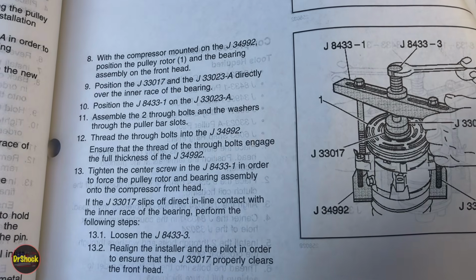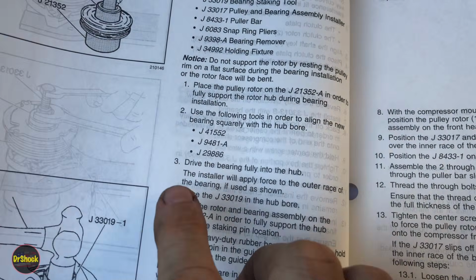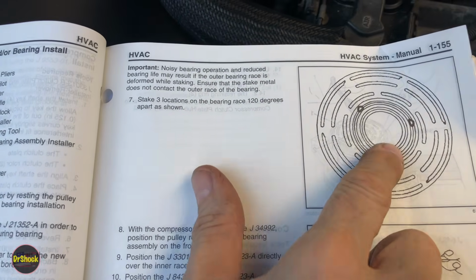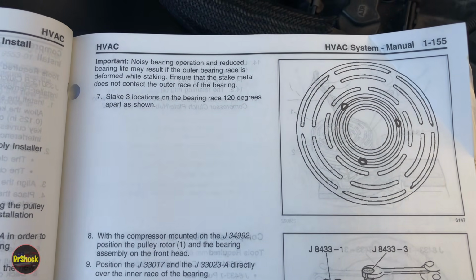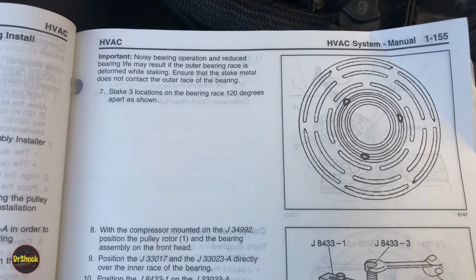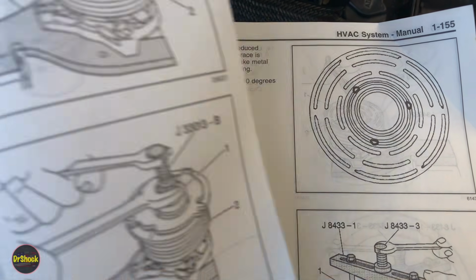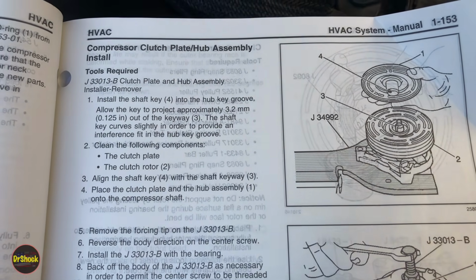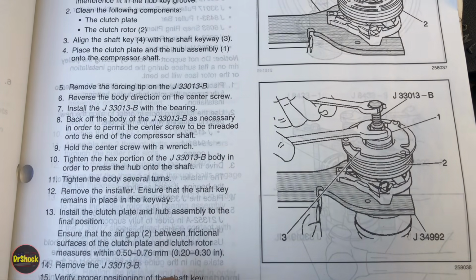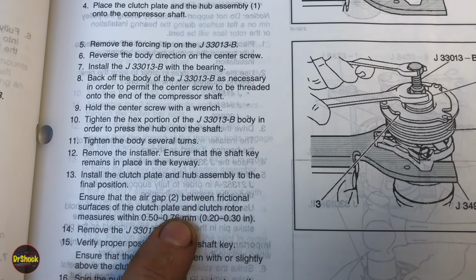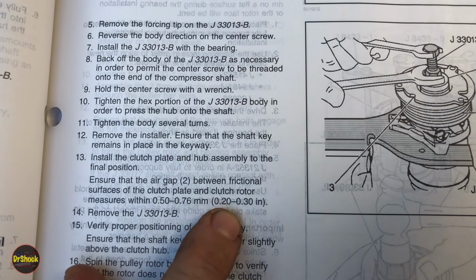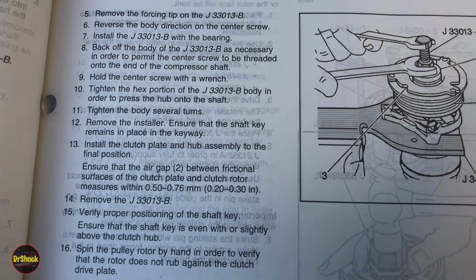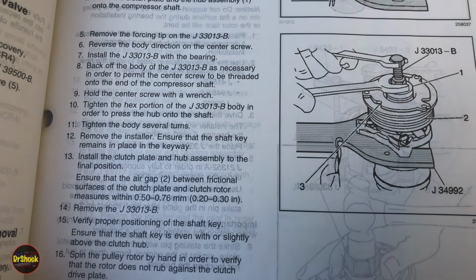And then they would have gone to this section to put the rotor back on. So we're not missing anything here. But they also would have staked the bearing and the rotor, something else that we didn't see on this version, so they don't do that anymore either to save money. And then when you get the clutch plate put back on using this tool here, which is similar to the aftermarket tool, there's the air gap specification from 0.20 to 0.30 thousandths of an inch. So hopefully this little bit of information in the service manual helps show you the differences between doing it on the bench and doing it on the vehicle.